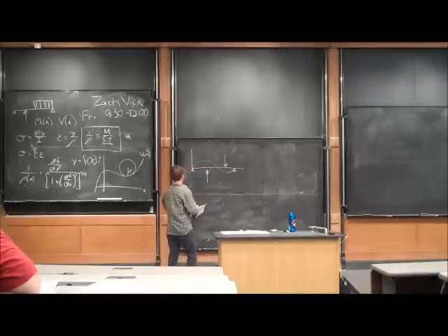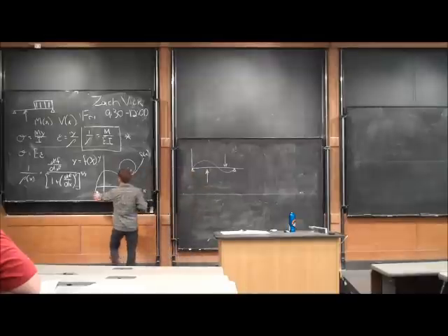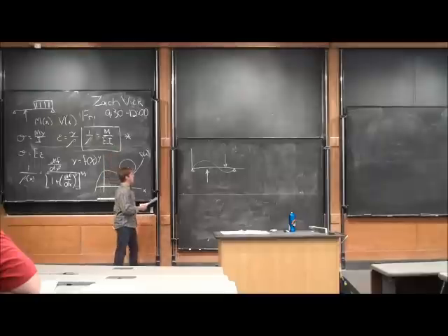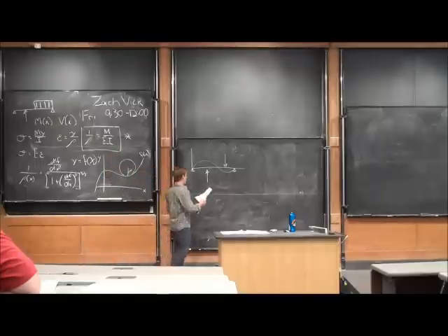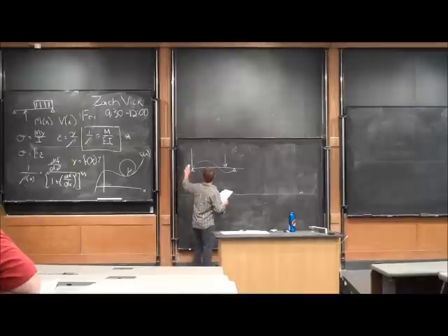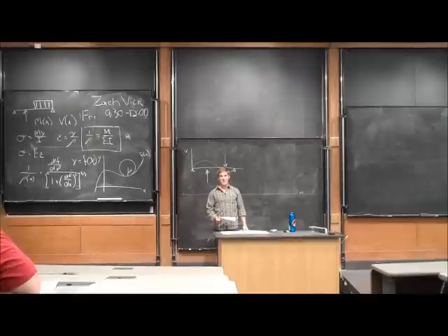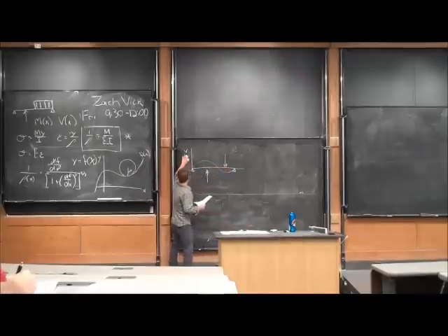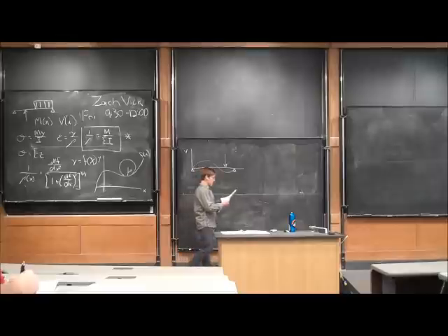So if we want to figure out how much that beam deflects, we can use this relationship from calculus and this equation that we derived last week to predict that deflection. In solid mechanics, we often use lowercase v as a deflection. It's confusing because uppercase V is the shear, so make sure you keep your uppercase and lowercase straight, because v kind of looks the same either way.